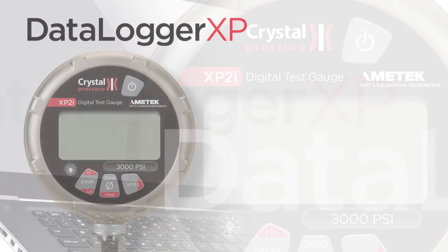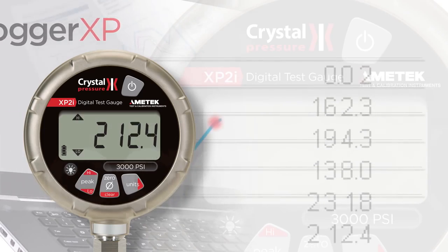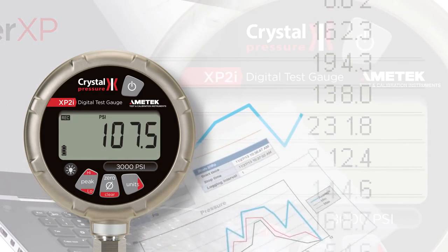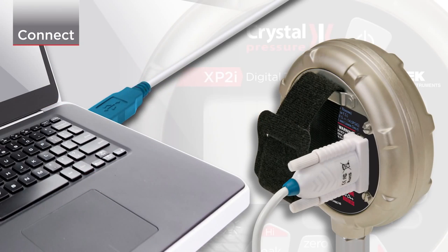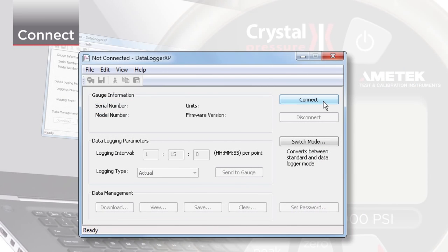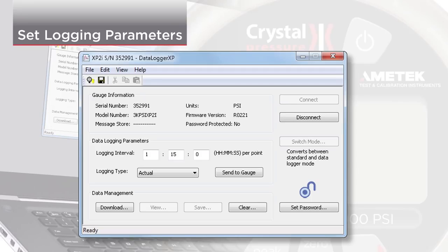XP2i has an optional mode called DataLoggerXP, which allows you to record up to 32,000 data points at up to 1 reading per second. First, connect your XP2i to a PC. Then select the logging interval. The logging interval is the amount of time between readings. The fastest logging interval you can choose is 1 reading per second.